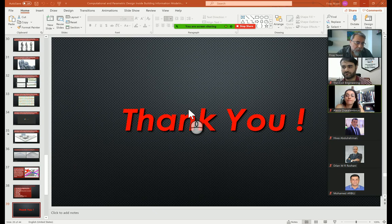It is easier to model because it doesn't have to bake the elements back automatically as geometry all the time. It is still an element. So the 3D thing you design is still a geometry, something inside the Grasshopper brain. It doesn't need to be exported as real geometries, as real lines, walls inside Revit or inside Rhino, whatever the platform. This makes it super fast.